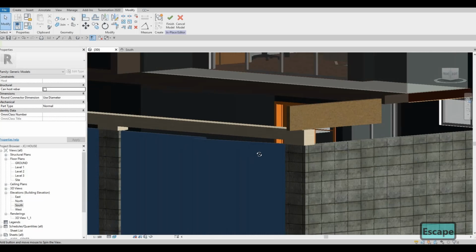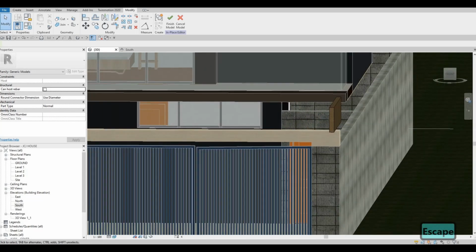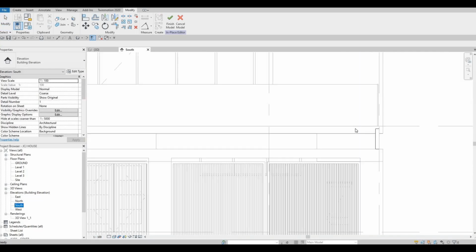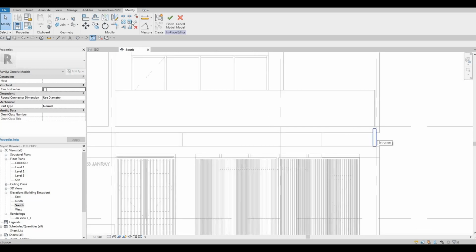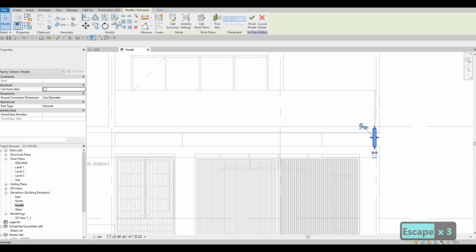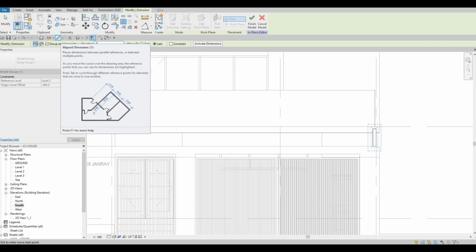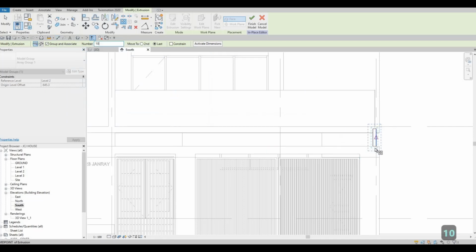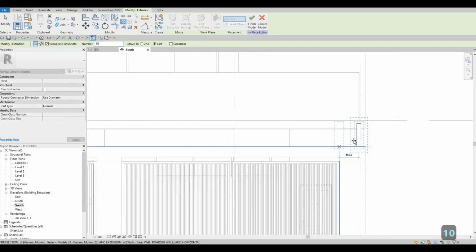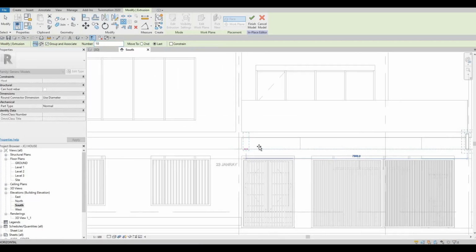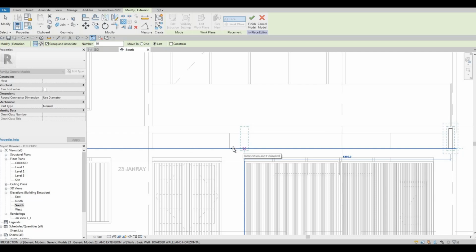So once we have it like that, what we could do now is go back to south, and then we could select not Scale but Array. Select Array, click on Last, and then we're going to change this here, probably around 10. Grab this one and then put it only right here.